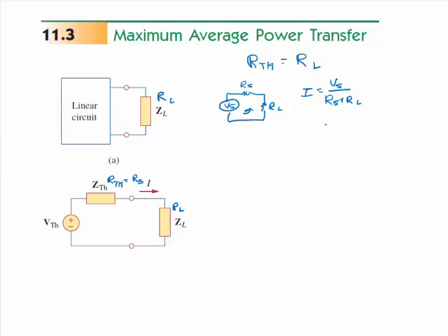But I'm going to just prove that this is when maximum power transfer occurs. Rs equals Rl for max power in RL. If I were to vary RL and calculate the power in the load, it would make a plot like this, and there would be a point of maximum power in the load, and that point would be when Rs and RL are equal.